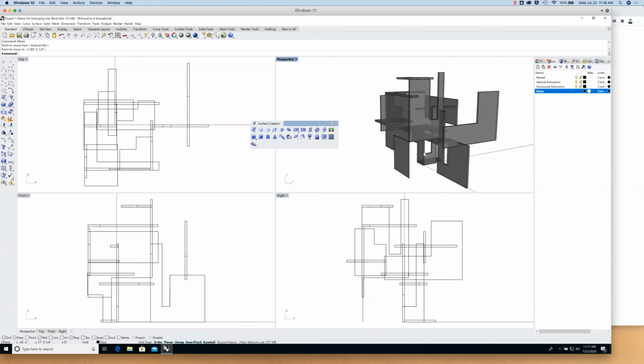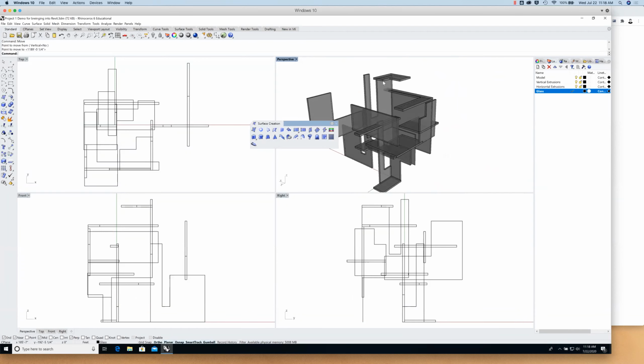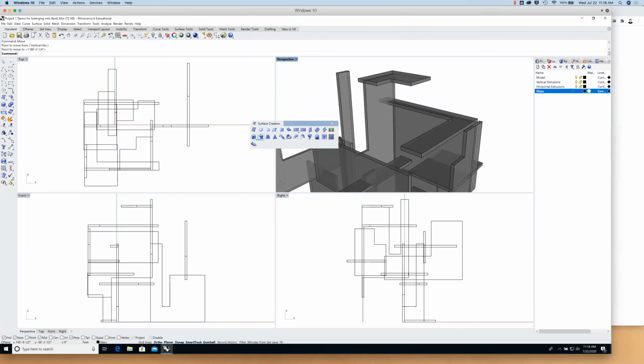All right. I think yesterday we also did something out here as well, right? So I did this funny corner condition and pulled those down. So I'll go ahead and do that right now as well. Go ahead and extrude, type in extrude curve. There we are. Once you start typing in extrude and you've used extrude a couple of times, it'll automatically guess that you're typing an extrude, and you can just hit enter without having to type the whole thing in all at once.